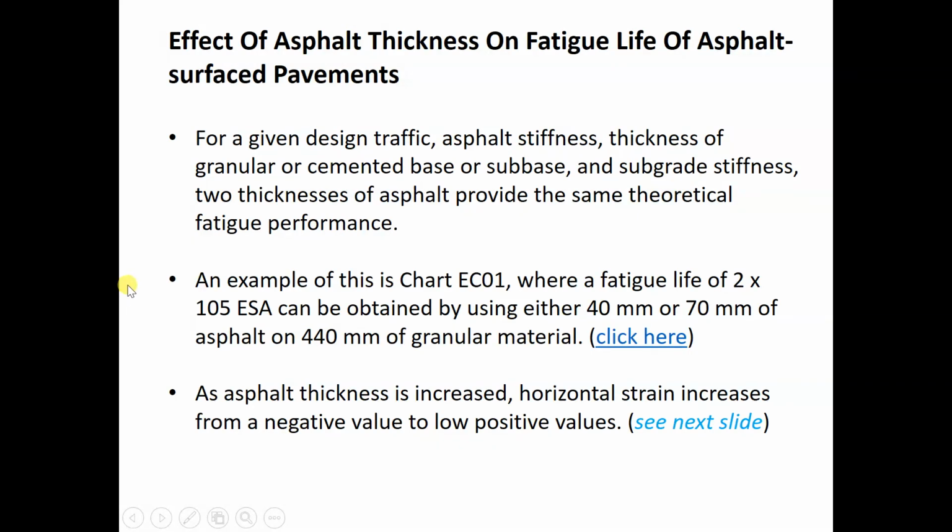For a given design traffic, asphalt stiffness, thickness of granular or cemented base or sub-base, and subgrade stiffness, two thicknesses of asphalt provide the same theoretical fatigue performance.